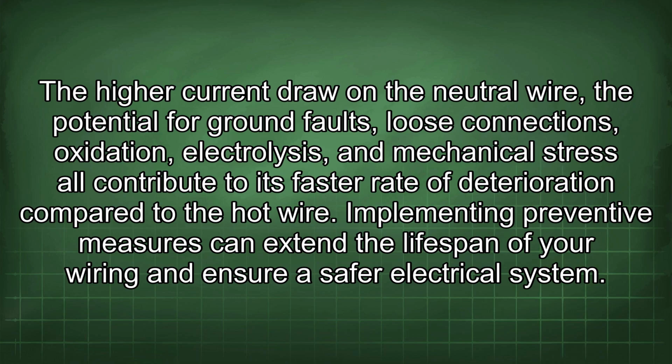The higher current draw on the neutral wire, the potential for ground faults, loose connections, oxidation, electrolysis, and mechanical stress all contribute to its faster rate of deterioration compared to the hot wire. Implementing preventive measures can extend the lifespan of your wiring and ensure a safer electrical system.